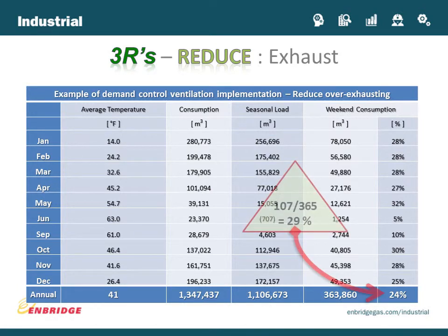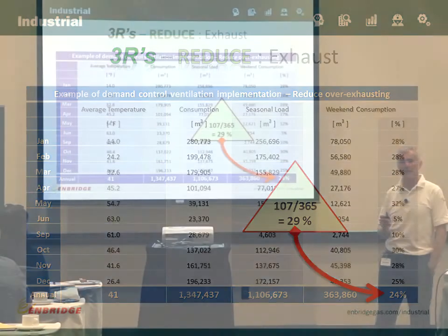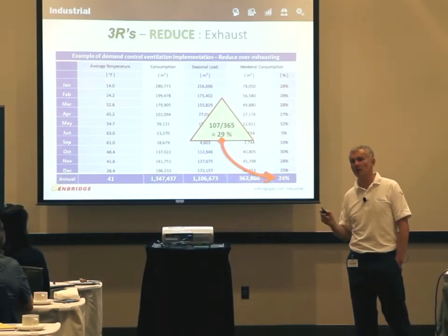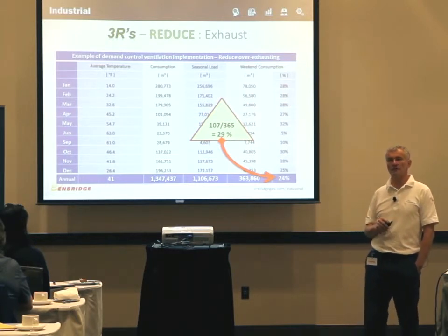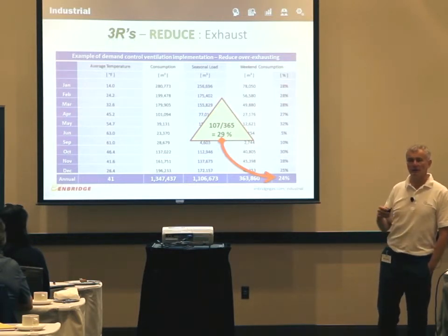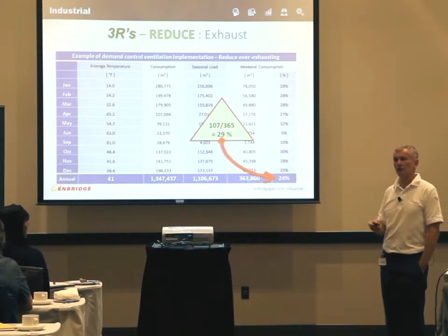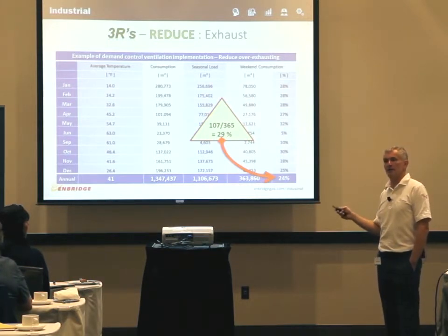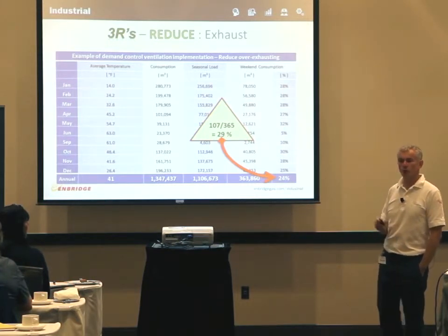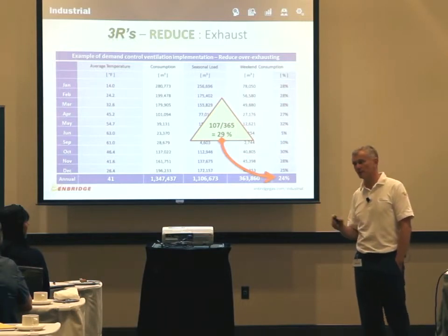Well, so why is it that 24/5 should give you 29% of your time throughout the year being off, yet 24% of your energy is used in exactly that time? He's like, oh, that's a problem. So we went back and looked at it. He came back on one of the Sundays that nobody was in and went by himself to take a look at it. Every single makeup air and space heater was on. Full blast. Not one person in the facility.